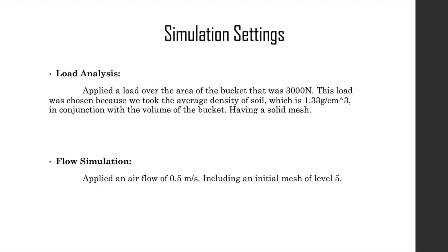For the wheelbarrow, we did 2 types of simulation study. We did a load analysis and a flow simulation. For the load simulation, we applied a 3,000 Newton force over the area of the bucket. This emulated having the weight of soil put on top of the wheelbarrow.